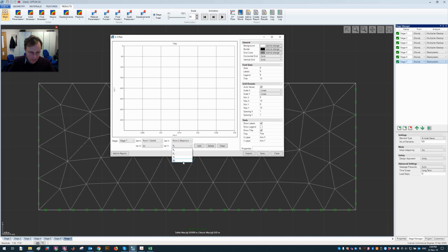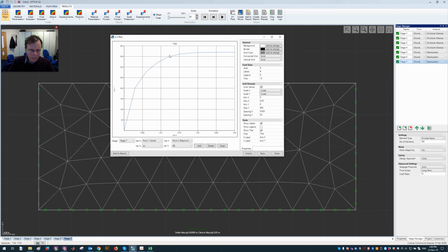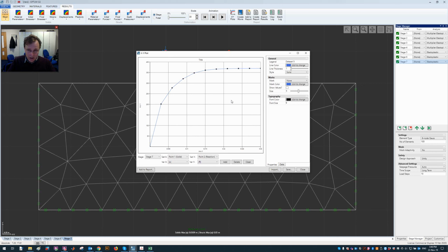Just due to the sign conventions, but we can plot the total reaction, and that's the one shown here. There will be, I guess, a small X reaction. That's very small. So this is pretty much the Y reaction. That X reaction is of course only due to the fact that the mesh is not completely symmetric, and it's very small. So that's another way of generating load displacement curves by displacement control. But the multiplier elastoplastic, well, both work. You can have, of course, cases where load control is more appropriate, and where displacement control is more appropriate. It sort of depends, but you can do both.